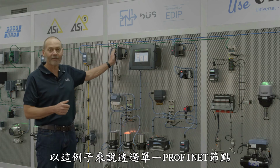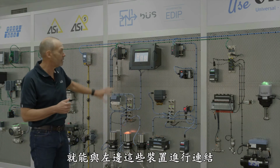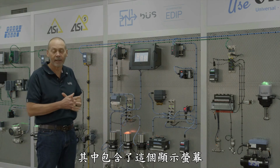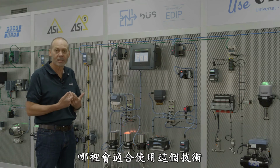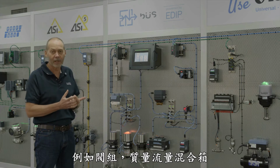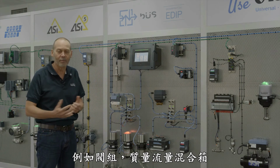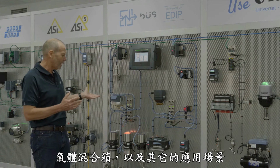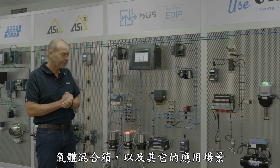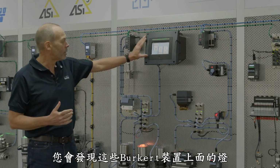So in other words, it makes wiring much, much simpler and reduces the total cost of ownership considerably. And then you only have one Profinet node, as an example, connecting everything that's on this side, including even the display. So that gives you a good idea as to where you might use this technology in things like valve clusters, as well as mass flow mixing boxes or gas mixing boxes, and other applications like that.